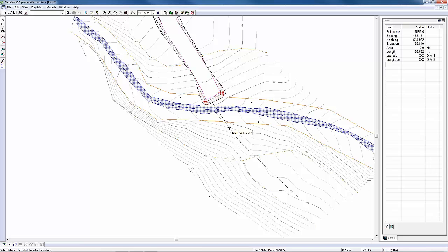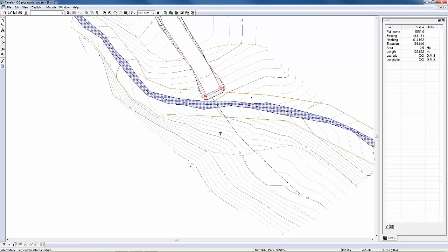I started in the design module, exported my road edges out, brought them into the terrain, calculated simple slope that grades down to the ground, hence forming my simple bridge abutments, merging the original ground with this new surface, saving the file, looking at it in 3D, and let's go on to the South Road now and do the more advanced bridge abutment design.